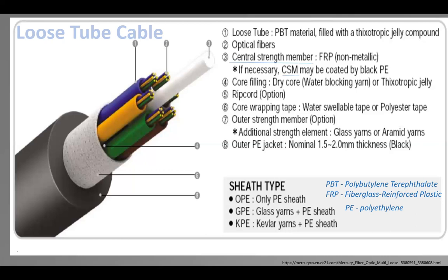These are the cables that carry the signal from one part of the city to another, from one city to another. Basically they are being used outside. So they have to be protected against the environment, and they are installed there day and night, all seasons through the year. So sometimes it's pretty hot, and sometimes it's pretty cold and whatnot. So the thixotropic jelly takes care of the temperature differences, so that there's no freezing going on, or expansions and contractions that would damage those cables, as all materials expand and contract when the temperature changes.